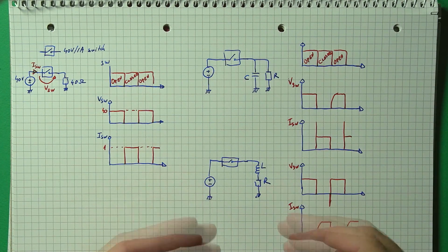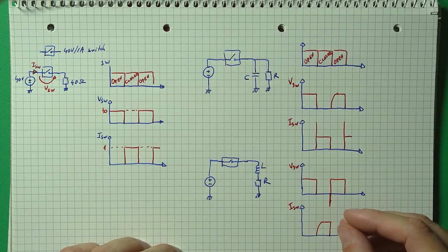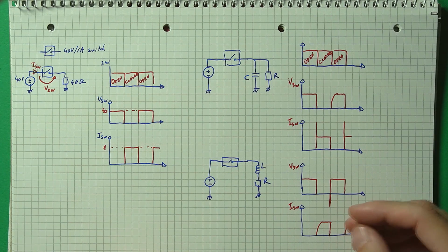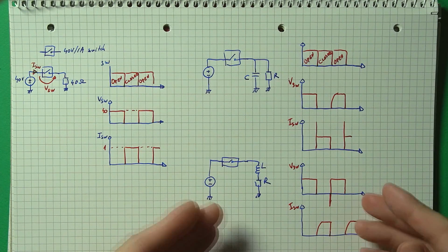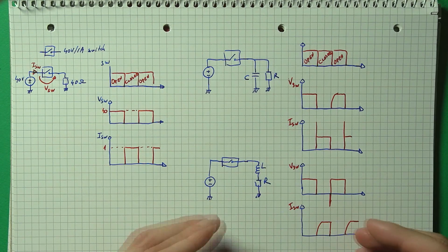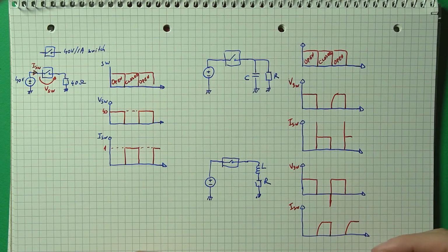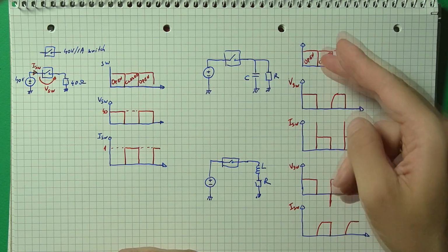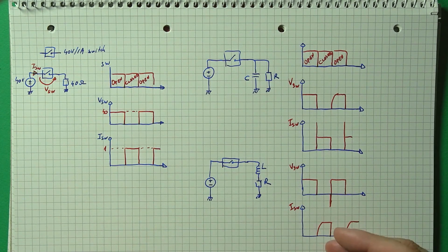On the other hand, when driving an inductive load, you will be getting a huge voltage spike, also known as inductive kickback, and this occurs since the current in the inductor cannot instantaneously drop to 0, so the energy stored in the magnetic field needs to go somewhere, and the inductor turns into a reverse voltage generator. When the switch is closing, the voltage instantly drops to 0, and the current slowly increases as the inductor opposes the change in flow of current.